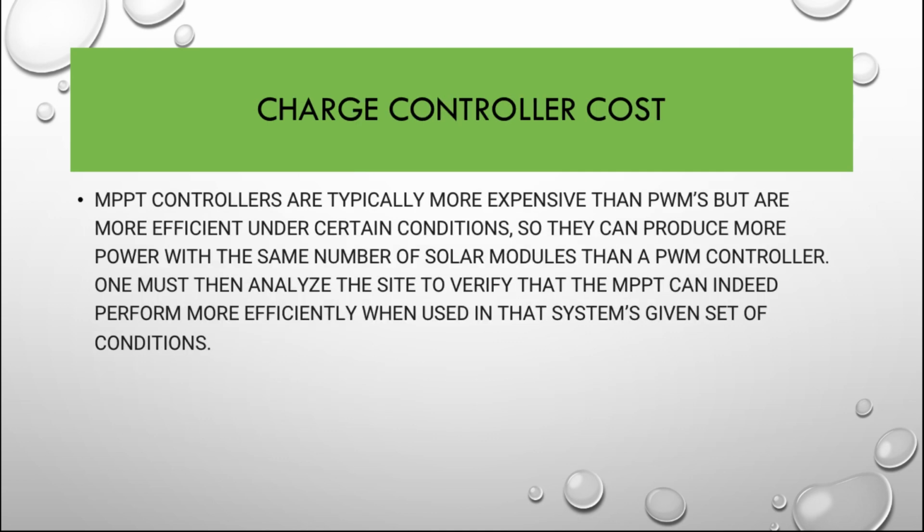Charge controller cost. MPPT controllers are typically more expensive than PWMs but are more efficient under certain conditions, so they can produce more power with the same number of solar modules than a PWM controller. One must then analyze the site to verify that the MPPT can indeed perform more efficiently when used in that system's given set of conditions.